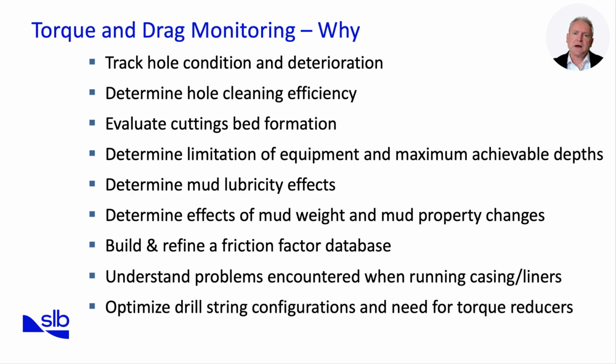Torque and drag monitoring is such a critical part of drilling operations. At its core, monitoring provides a continuous assessment of hole condition and deterioration. By tracking pickup and slack-off weights, we can detect early signs of increased drag that may signal developing tight spots, cuttings accumulation, or borehole instability. Another major benefit is evaluating hole cleaning efficiency.